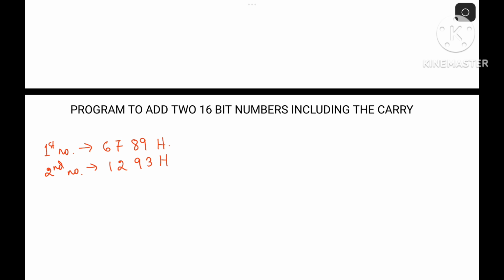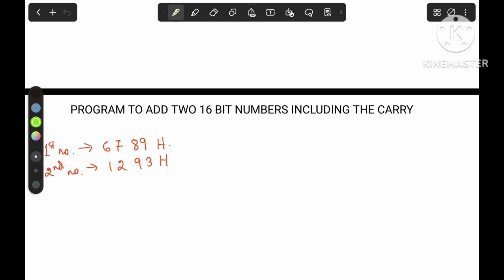Okay, so what we have to do is we have to divide these 16-bit numbers into bytes as lower byte and upper byte.